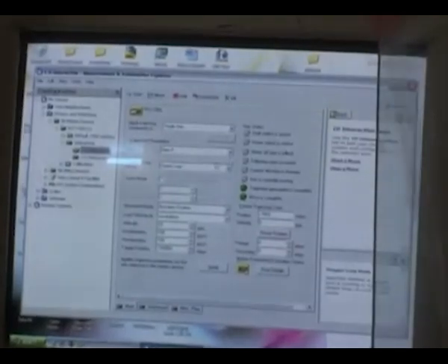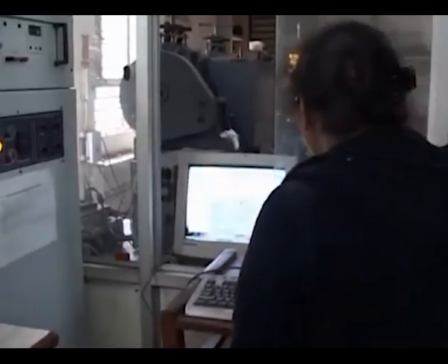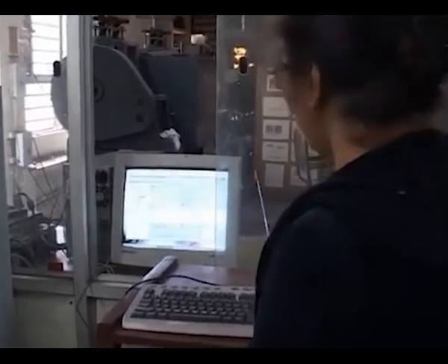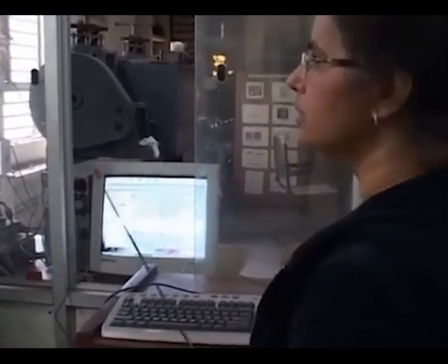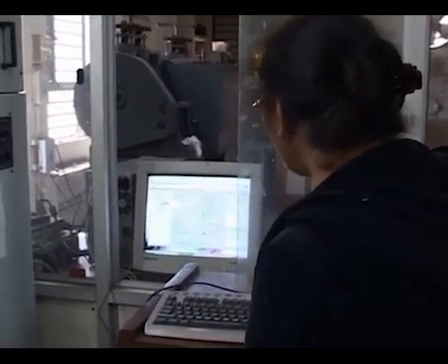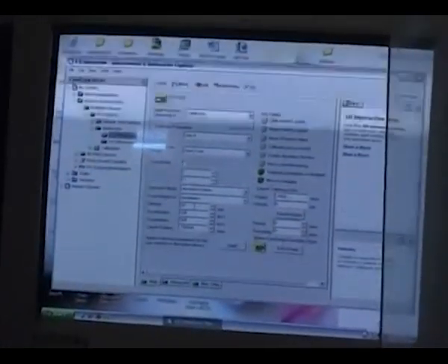One can see right now the Z motion. I am programming it. So here is the single axis motion mode. Axis 8 is configured to the Z axis assembly. We are using open loop control. There is no feedback from the stepper motor as such. The velocity I am setting to be 20 RPM.